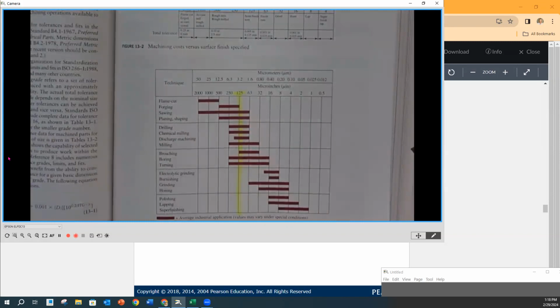Good. Okay. Any others? A lot of the time on templates there'll be a check mark for the surface finish and a default of 125 or something at companies. So if you just put that surface finish mark on there, sometimes it'll default to that as well. Yeah, that's a good point too. Then you don't have to put them all on all the time. You still would put them on, but it's in the notes section, like a blanket saying for any finish marks, they're all blah, blah, blah, unless otherwise specified. Right, good.